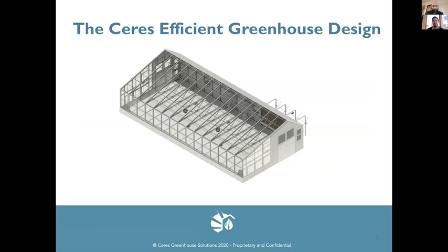The simplest design facet that we use is just orienting the building properly. Traditionally, many greenhouses are oriented in a north-south orientation with fully glazed roofs. We orient directly to the south, or with a little emphasis on the southeast if possible, in order to capture the full potential of the sun.